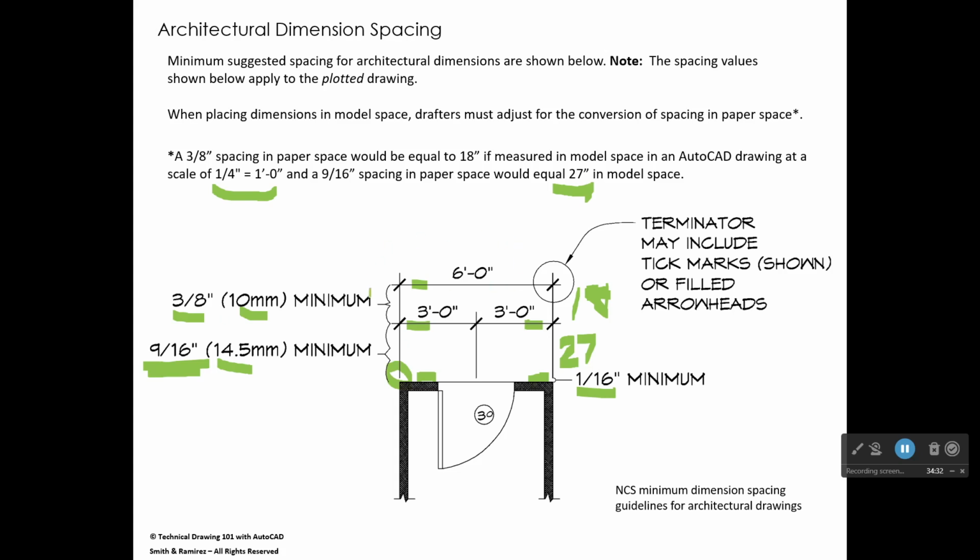So because we draw full scale, when we draw a floor plan in model space, if we put our dimensions in model space, we have to also scale up, right?